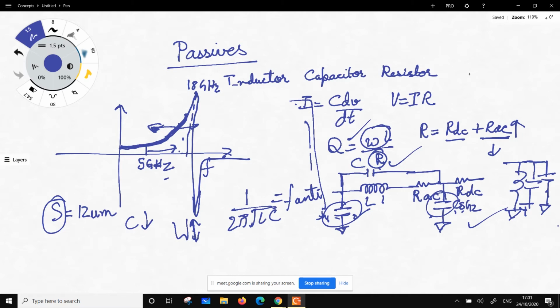Okay, another thing which you can do to reduce the capacitance is this: most of this capacitance comes from an underpass. So if for example you have a coil on M1, or let's say M2, and you are coming out on M1, instead of M1 you come down on M0. So that way the distance between the two metals is more. So whenever there is an underpass, basically the coils are running like this, right? Then there is an underpass.